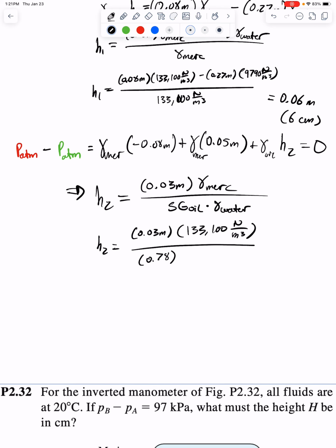Yes. What is gamma and how do you find those values? Oh, so gamma refers to specific weight, and those are given in tables usually. All specific weight refers to is, you saw this here where I said Bernoulli's equation, rho g h. That rings a bell, like for potential energy, or gravitational energy, sorry. That rho g term, that's all that gamma is. Gamma is rho times gravity.